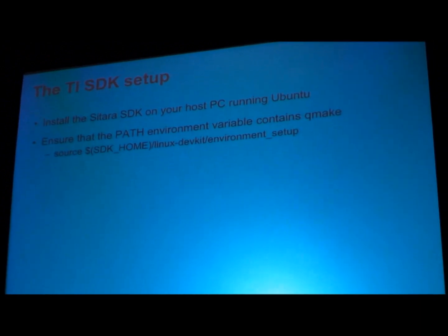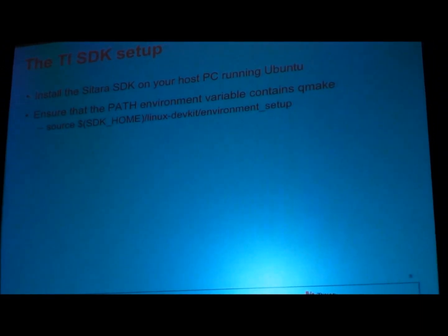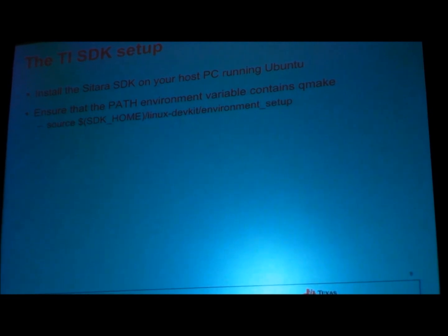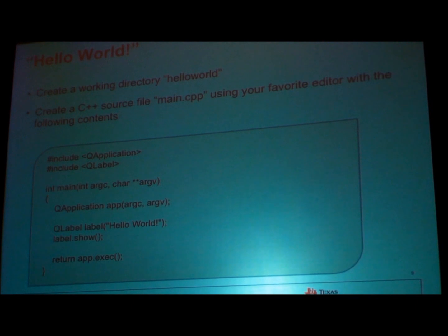But there is a bundled set of libraries and toolchain, delivered in an SDK environment for you, and you would just install the Sitara SDK onto your PC running Ubuntu. Ubuntu's required. The expectation here for this SDK is how it's tested, and then simply just source your environment path. Right, so all the environment variables you need in order to utilize the tools from the command line are just in an environment shell script.